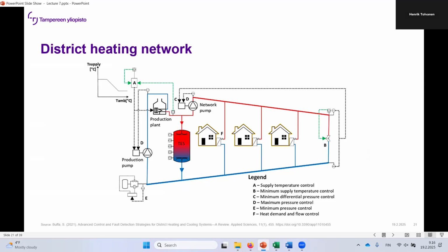And based on Juhani's preliminary results, it seems that for a system that hasn't originally been built for operating under lower temperature levels, it's unfeasible to start decreasing the supply temperature. The savings are so minimal, and it might cause problems at the customer end. If it's not being built for that, then there's going to be a problem. But as I said, preliminary results.